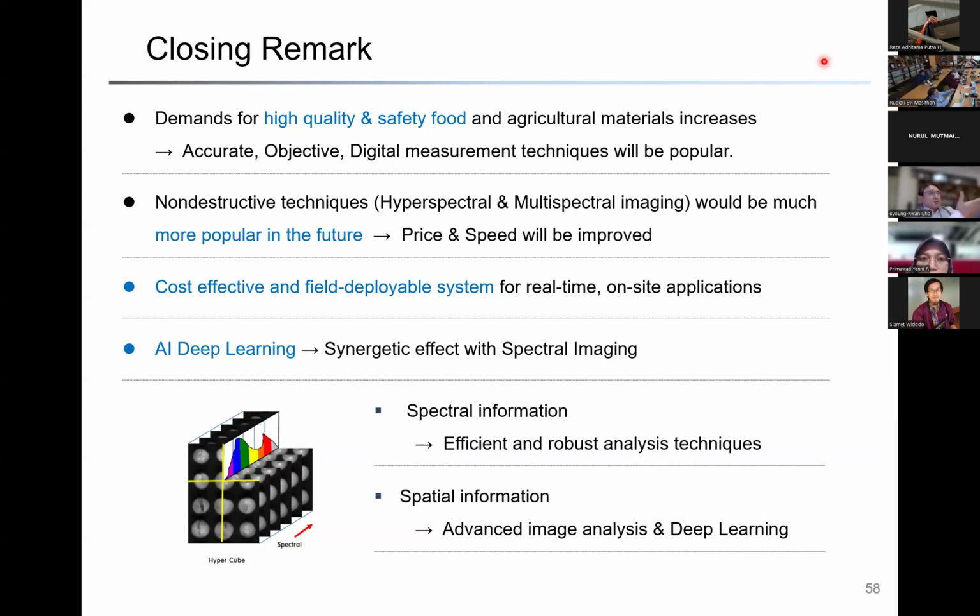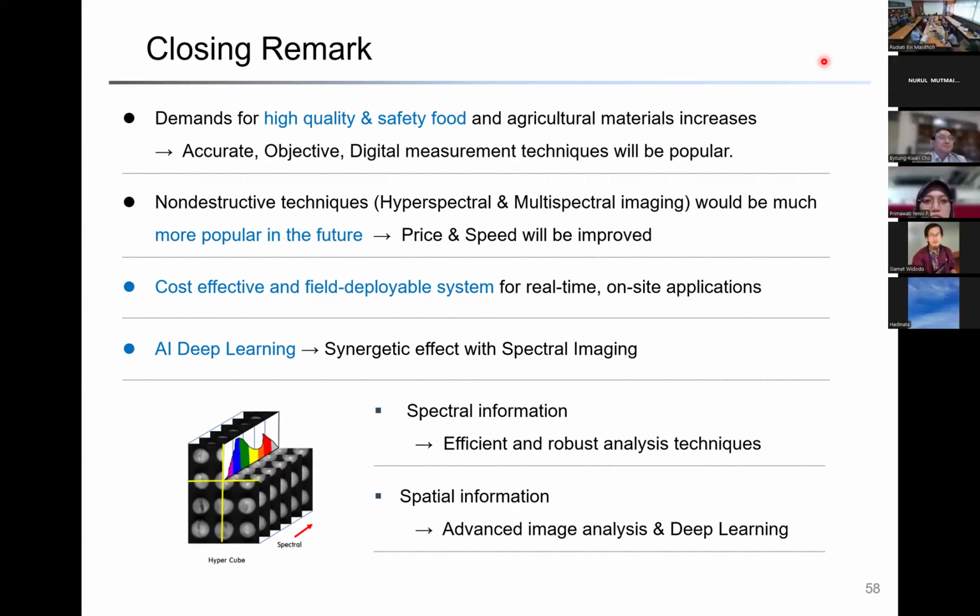So you can decrease the distance, maybe, or you can block the outside of the sensor. That is another way, because we don't want unwanted signal. We can color the blocker black, and also the background of the samples. Black would be fine because it minimizes reflectance.